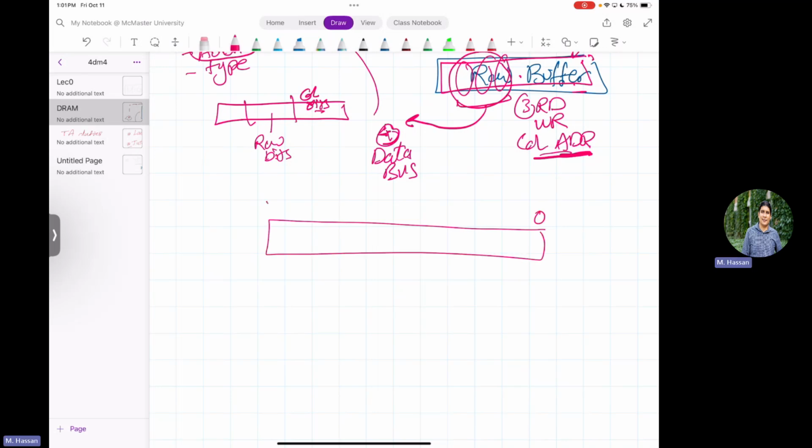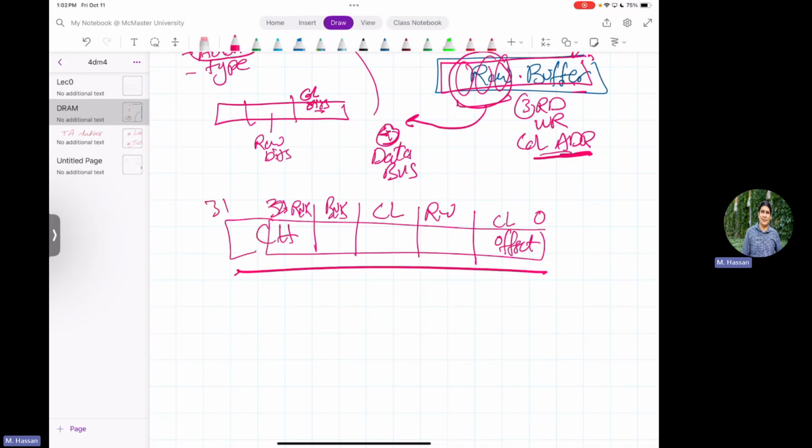this is your 32-bit. Out of this address, you determine, okay, this is my cache line offset. This is my row bits. This is my column bits. This is my bank bits. This is my rank bits. This is my, well, let's say this is the 32. These are my channel bits, right? So it breaks down the address into the low-level segments of the DRAM to route it to the correct bank, correct row, correct column, etc. Good. This is called address translation.